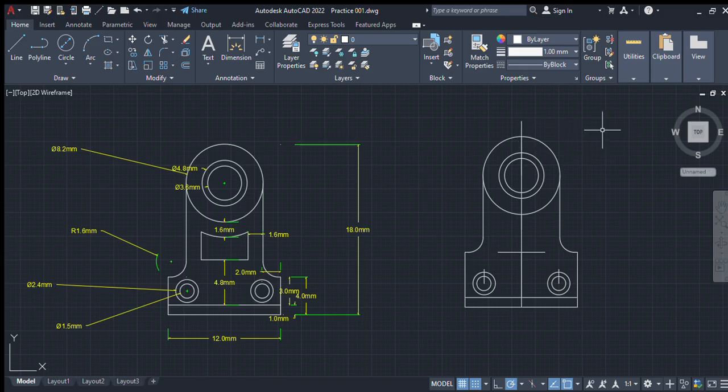So now the question is how are we going to know the diameter of the circle. It's very simple. We are given from here to here is 1.6, so they're giving us hints. That means from here to here will also be 1.6. So just add the 1.6s together and add the 8.2 to get the diameter of this circle that was not given in the PDF. So 1.6 plus 1.6, that is 3.2. So 3.2 plus 8.2, that will be 11.4. So 11.4 is our diameter.